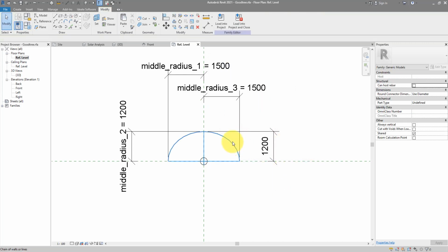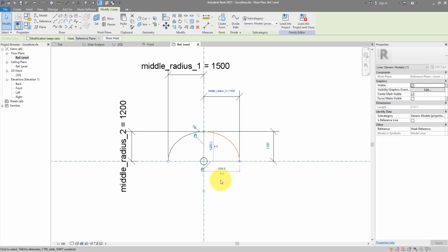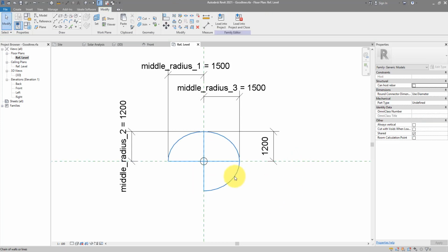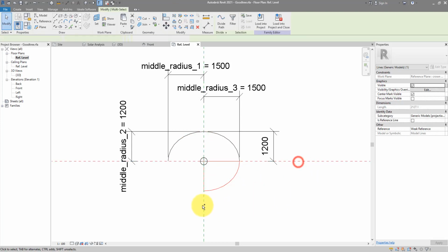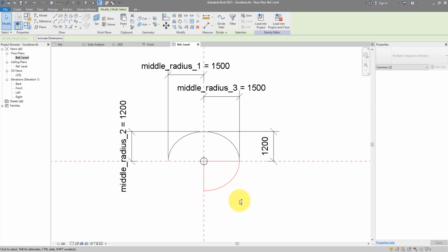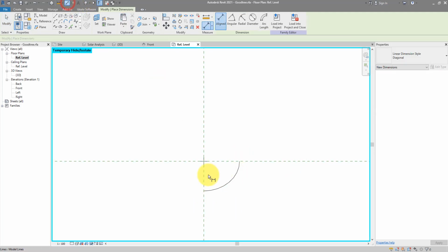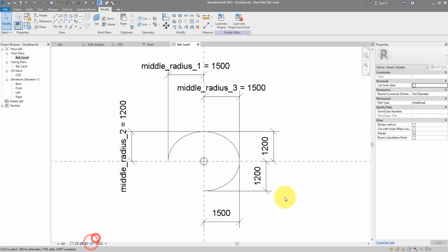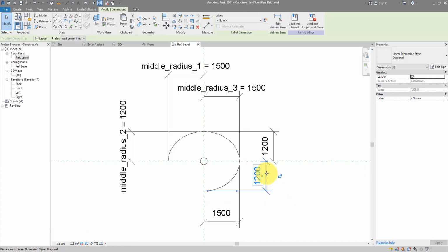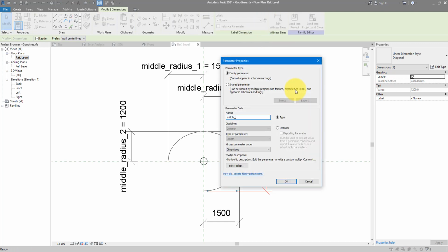Next step, you guessed it, we can now mirror that last arcs down to get the 3rd quadrant. Like so. And like before, I can now select the new quadrant along with the plane and isolate them. I can now make those dimensions again. Reset the view again. And now I can say this should be the new distance. It should be middle radius 4. Should be instance as well.